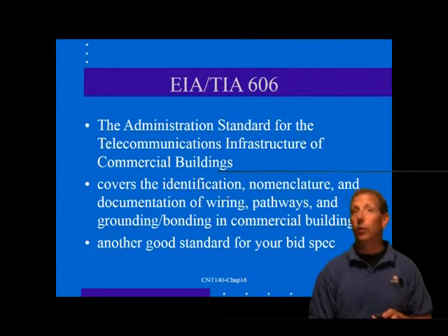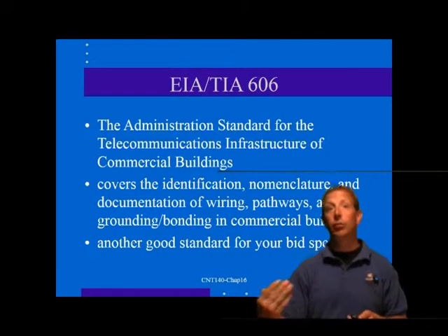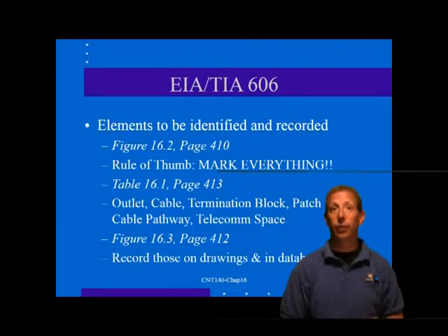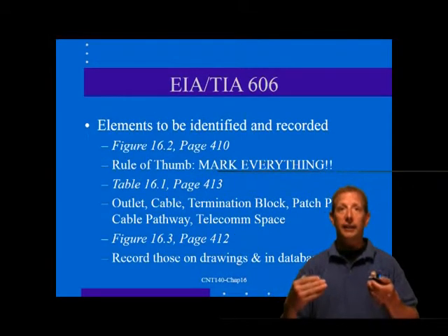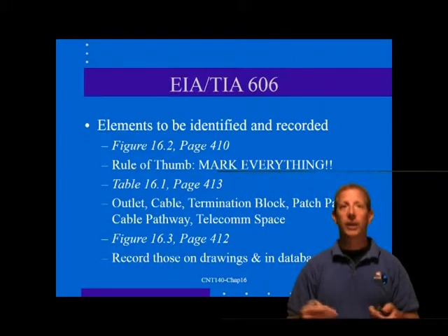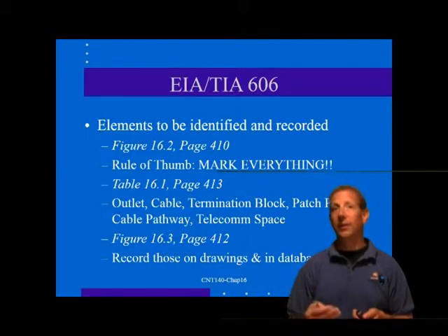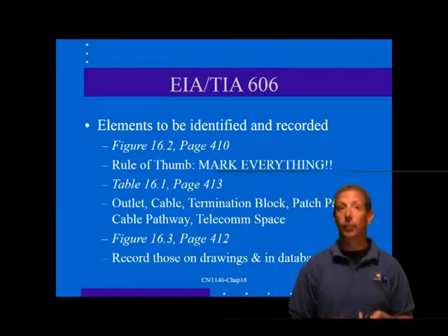Large installations will benefit from the labeling of cable pathways such as ducts, sleeves, cable trays, and conduit. Raised floors, while not directly marked, can also be identified in drawings showing grid numbers for each work floor area. Work areas and telecommunication spaces should also be identified with a marking at the entrance to the area. For many buildings, this requirement is easily handled by existing room numbering.